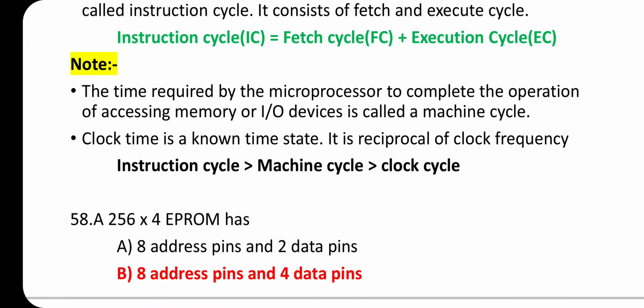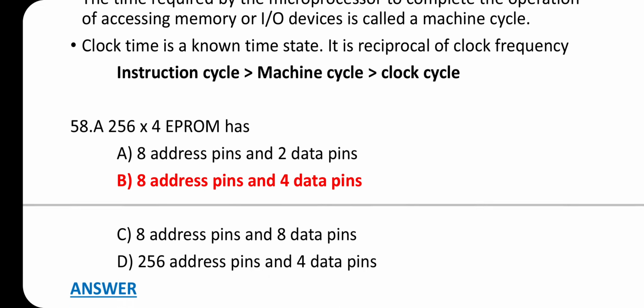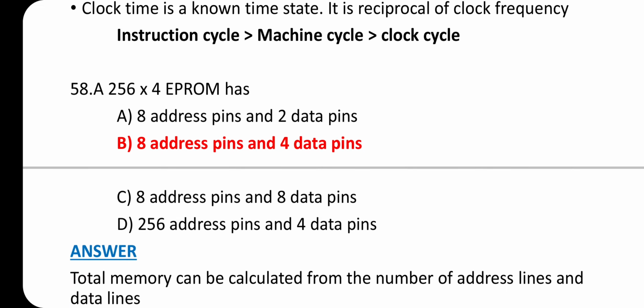Steps in the instruction cycle. First of all, the opcode is fetched by the microprocessor from a stored memory location. Then it is decoded by the microprocessor to find out which operation it needs to perform. If an instruction contains data or an operand address which is still in the memory, the CPU has to perform a read operation to get the desired data. After receiving the data, it executes the operation. The correct sequence is first fetch, second decode, then read effective address, then execute.